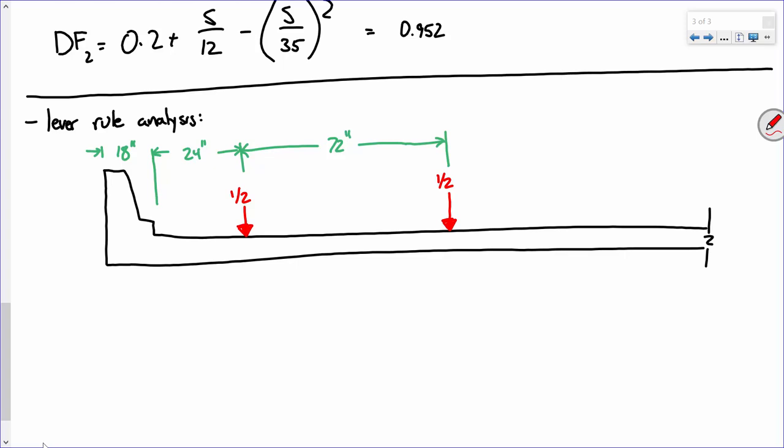Okay. Now, from the edge of the deck to the exterior girder is how far? Somebody else had given me that number earlier. That was the 3'6", right? So that's 42 inches in, where that exterior girder is. Now, just by sheer coincidence, that's actually right under that load, because the dimension from here to here is 42 inches. And that just happens to be 18 plus 24. That really truly is a coincidence. Okay, make sense?